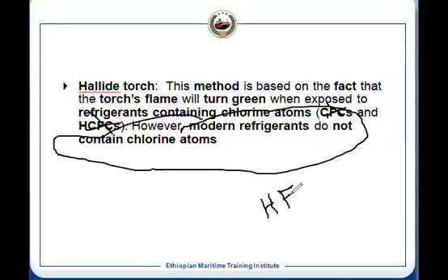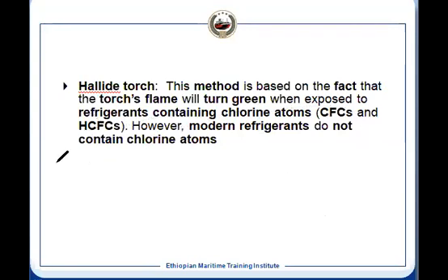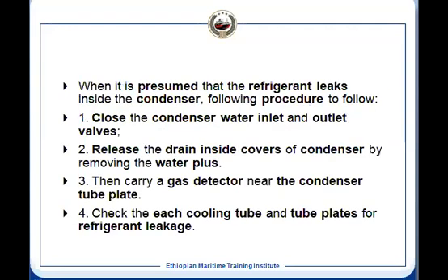Suppose we are using HFC because it is a requirement since 1st January 2020, but the previous stock was there. Now, if you want to use this to detect it, it will not detect because it does not contain the chlorine atom. So this is another method of checking the leakage, but for modern refrigerant, we cannot use this.